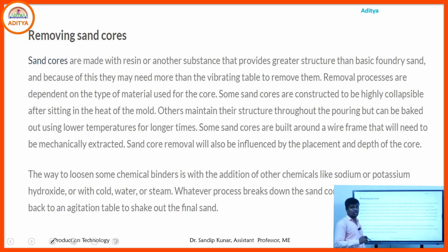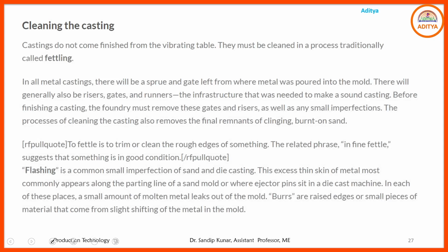Another step is removing sand cores. After solidification we remove the sand cores, which we sometimes use for creating internal features in that particular product. So after removing the mold and molding box and other parts, we remove the sand cores. Okay, then after removing the sand cores, finally we have got the product.